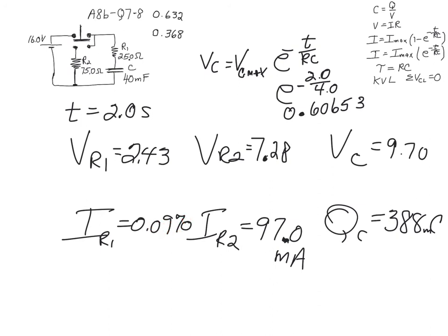amps. And then the same factor times the 12 volts gives me this, and that factor times the 4 volts gives me this. So I'm just using this equation again and again on all these different quantities, and you can see if I add these together, I get 9.71. So there's a little bit of a rounding error there. In other words, these two voltages have to equal this, because the sum of the voltages in this circuit now have to be 0.